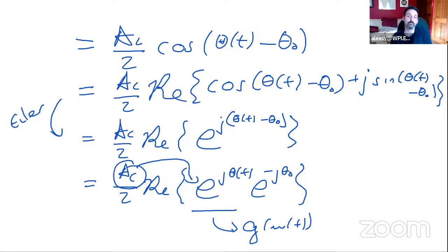And then, very importantly, the ability to apply trigonometric identities, as well as working with the real operator and manipulating the mathematics in order to go between the two domains. And also the practicality of using, once you get up to a passband, techniques such as low-pass filters to remove double frequency terms in order to extract out the desired signal, which at the end of the day is at baseband.